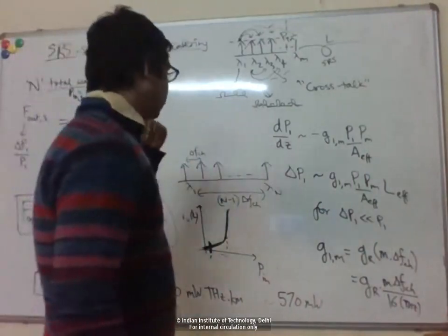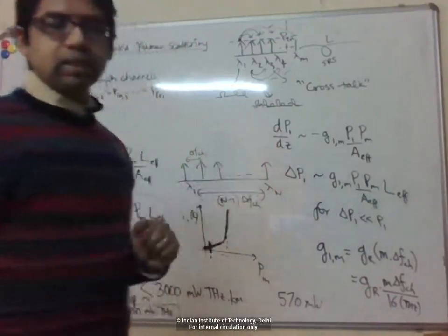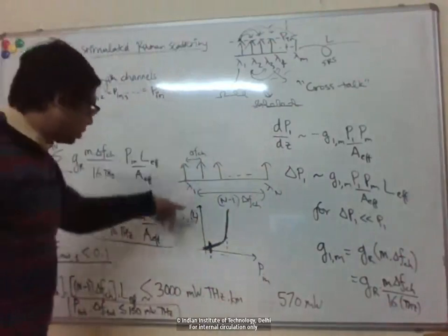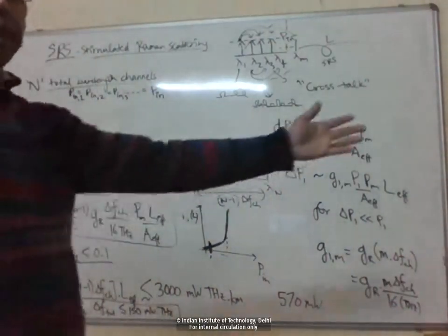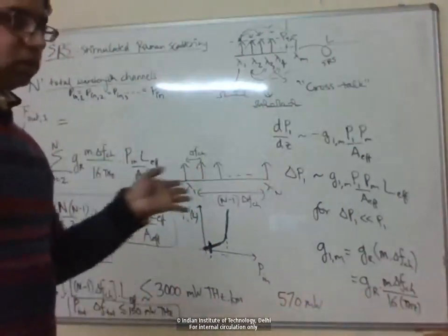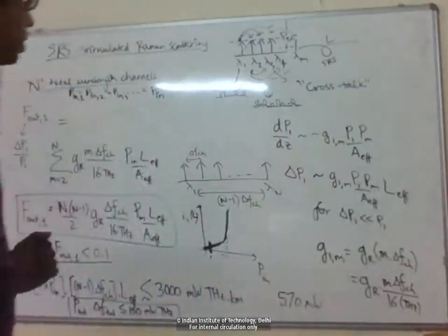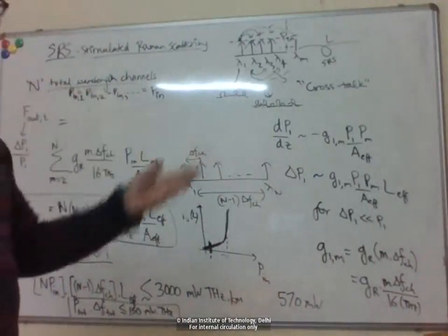I could just increase my data rate forever by putting more and more channels. But here you see that as I increase the number of channels, the power per channel has to go down, right? So that will again limit my link length because given the attenuation, for a particular SNR at the receiver, if my input power is restricted, then that restricts my link length.